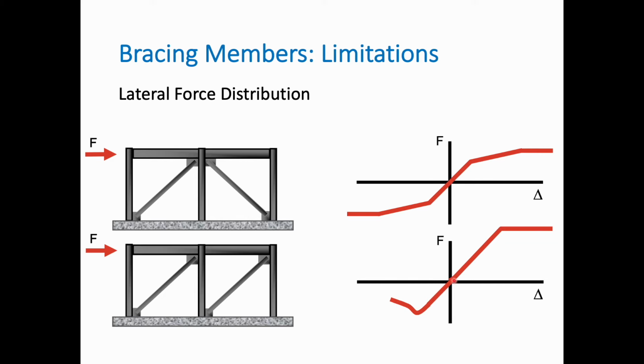So we would expect that if we reach this high strength here, we will have a remaining elastic strain, which will be enough in certain cases to reach the inelastic capacity of the bracing in the opposite direction. So that said, this is a bad design for a bracing, and in most cases we're trying to avoid something like that, and we go for a symmetric bracing.